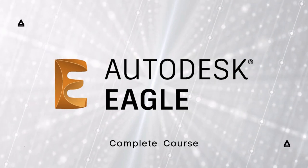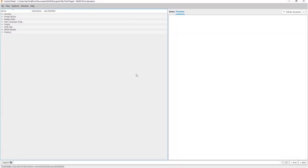After we learned about how to make symbol libraries in the previous video, now in this video we will continue to learn about how to make footprint package libraries in Autodesk Eagle. Footprint packages serve a super important purpose when used on your PCB layout, offering a set of paths that provide both electrical connectivity and a way to solder parts onto your board.